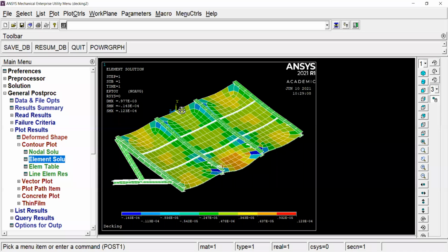Right now, the factor of safety is around 20. That's way too high for something like this. Maybe you'd be looking at a factor of safety of like 2. So then you can start to refine your design, refine your model. And that's what the assignment's all about, using finite element analysis to help you decide what is your best design that you can go for.